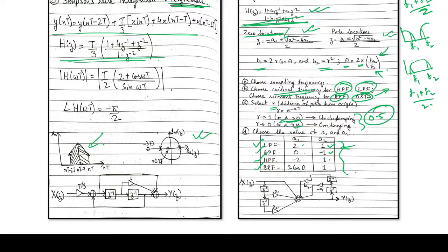And this is the very simple direct form 1 realization method to realize the filter. So you can see we can design a two pole digital IIR filter quite easily by this method. You will not get this method in many of the books, but if you are working in a lab and you want to design something, this is one of the simplistic ways to design your filters. With this we will stop today. If you have any questions, we can discuss.